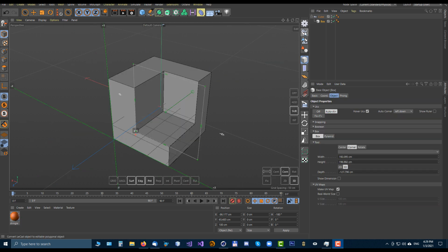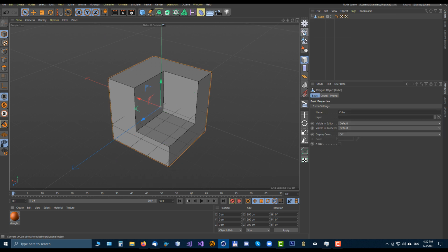The second command, for conversion of a LwCad object into a polygonal object, is even more important, especially if you are using parametric objects which are dependent on a parent or a child. You have to use this conversion command, because if you apply it, it will convert all objects properly and delete the remaining modifiers which should be deleted. Cinema conversion doesn't know how to handle this properly.